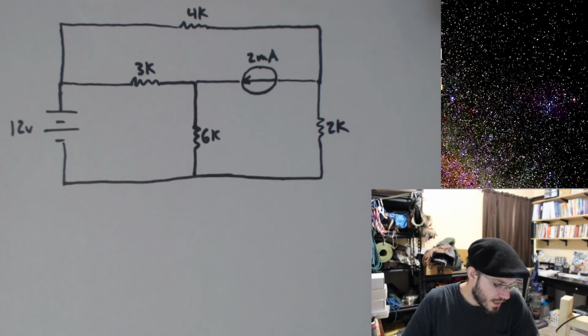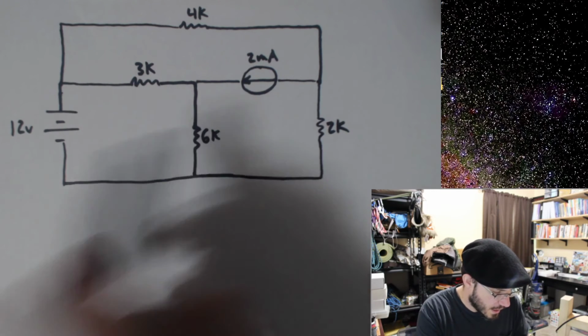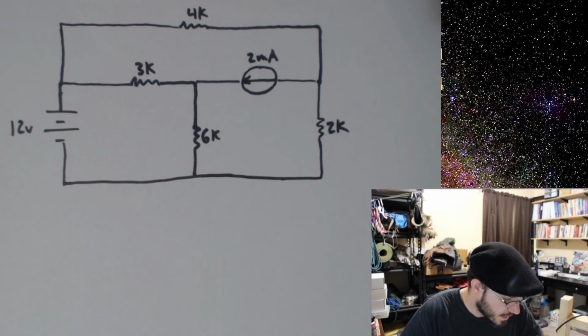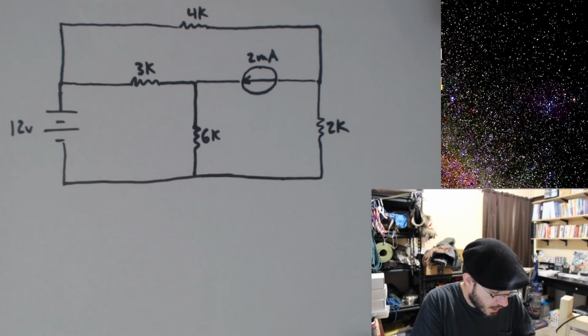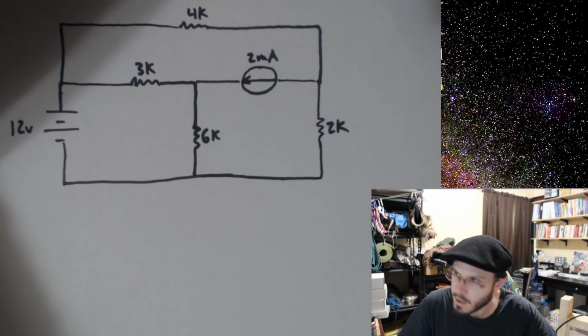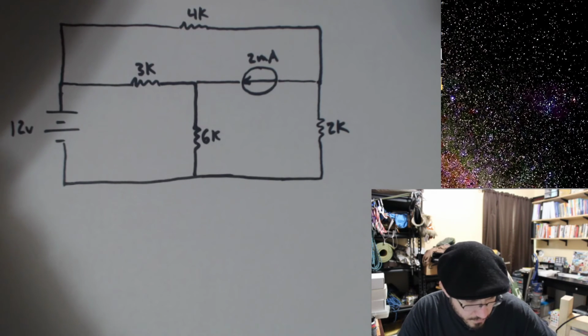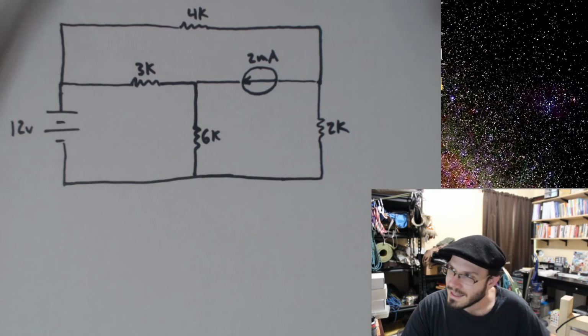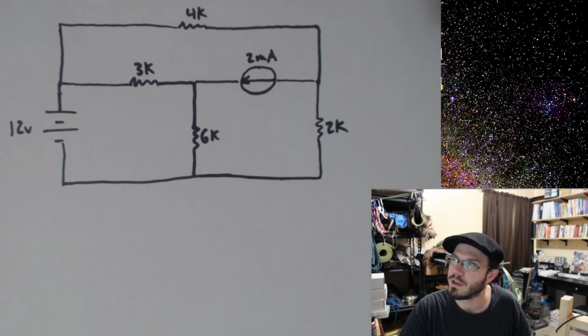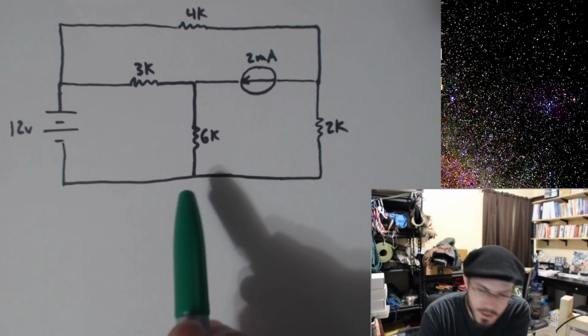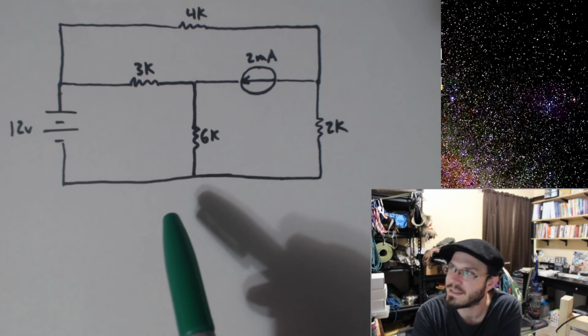So here's a great example where nodal analysis is going to allow us to solve this, and we really couldn't solve this too many different ways. Okay, so we're going to start off with step number one: let's assign the reference node. I'm going to try and pick the reference node someplace on this circuit to call 0 volts that makes sense to me.